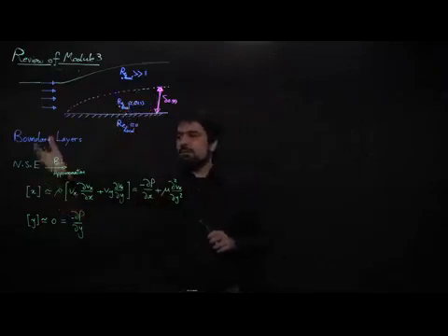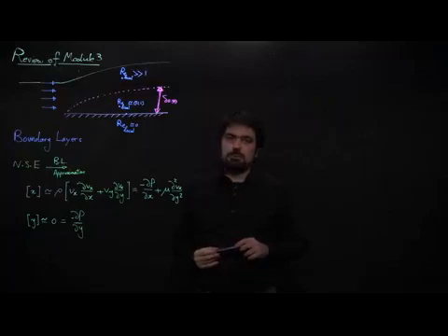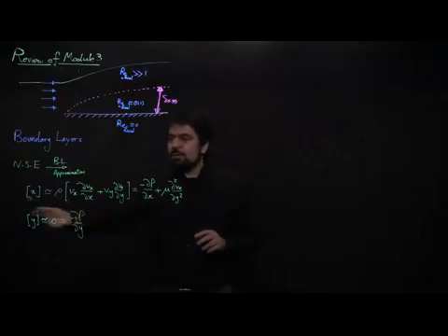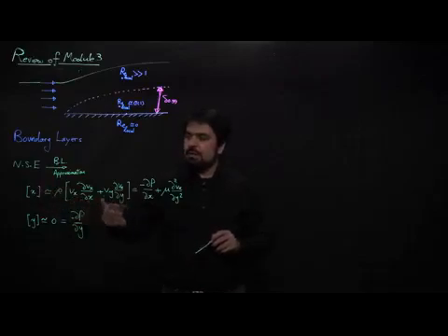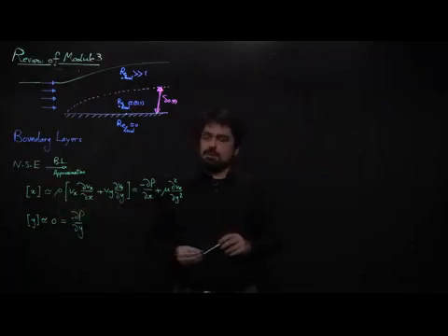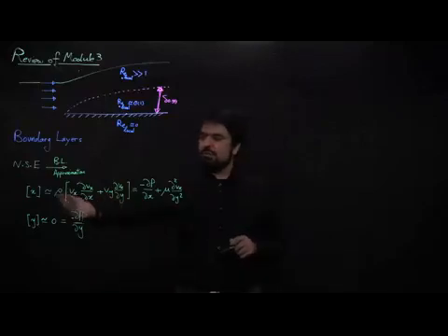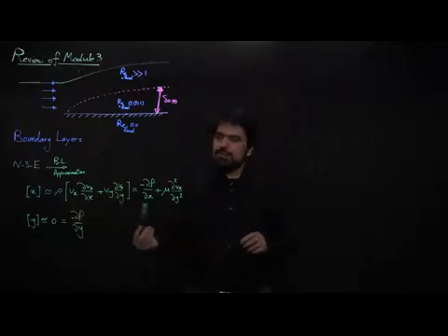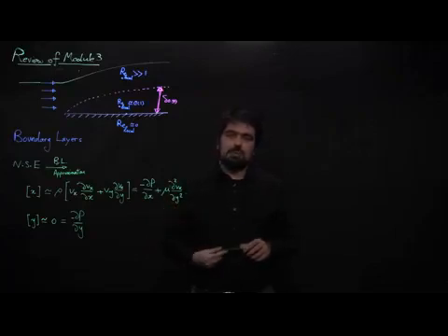That's what brought us to the boundary layer approximation of the Navier-Stokes equation. For a 2D flow, we found that the x component and the y component can be approximated in this manner. In the x component, we have the convective terms for acceleration of fluid elements. Since the problem is steady state, we don't have the transient acceleration, only the convective acceleration. On the right-hand side, we have the pressure gradient and the dominant viscous term, which is the second derivative of Vx with respect to y.